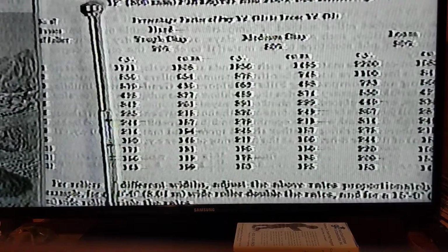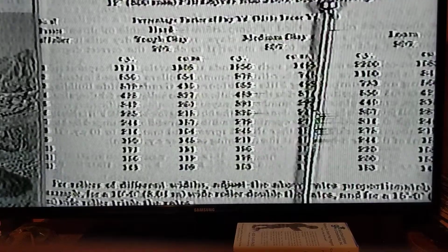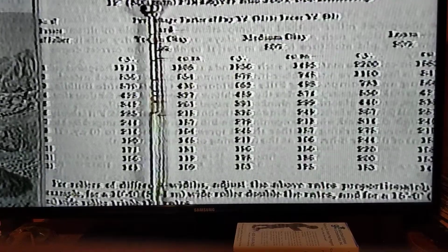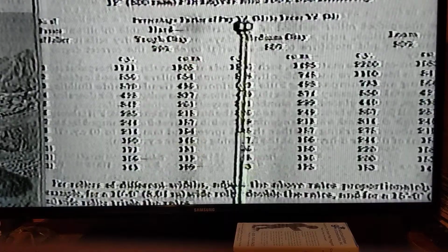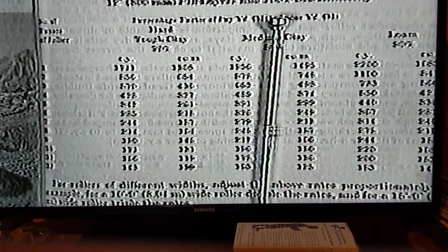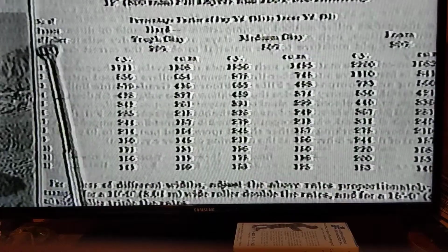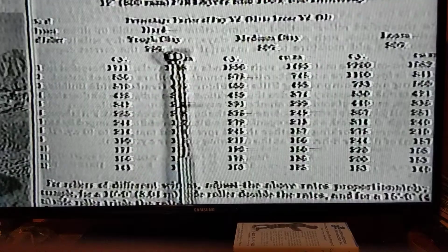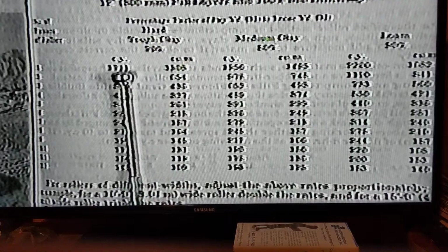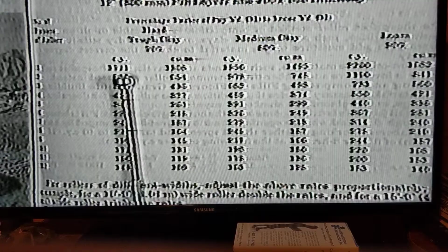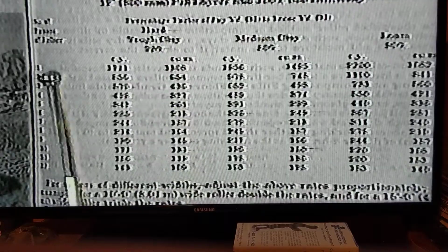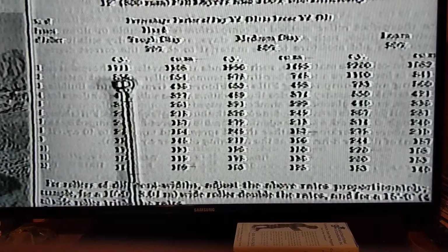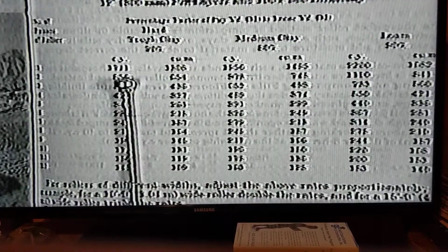In this case, we're talking about the rate of a sheep's foot roller compaction in cubic yards per hour based on a 5-foot wide roller going 2.5 miles an hour with 12-inch lifts and 100% job efficiency. So for example, if I correlate the number of passes, let's say one pass, with tough clay, I will see the number 1711. What that means is that given the conditions of the name of the table, all of those conditions match, and given a one pass over this land, I'll be able to compact 1,711 cubic yards of material per hour.